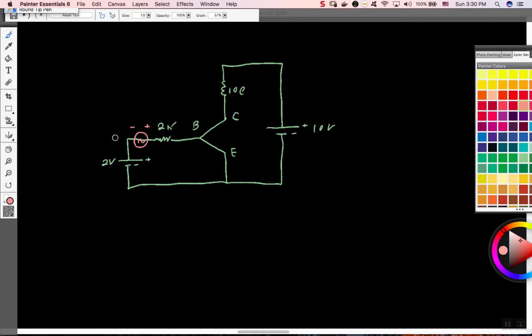Here there is a problem with applying the principle of superposition because the transistor is a non-linear element, and the principle of superposition does not work on non-linear elements. As a result, we would like to, for example, take the 2-volt and 10-volt voltage sources, analyze the currents and the voltages, and then take just the AC source. So we can take those two sources at a time, see what happens, then remove them, put the AC source alone, and see what happens.